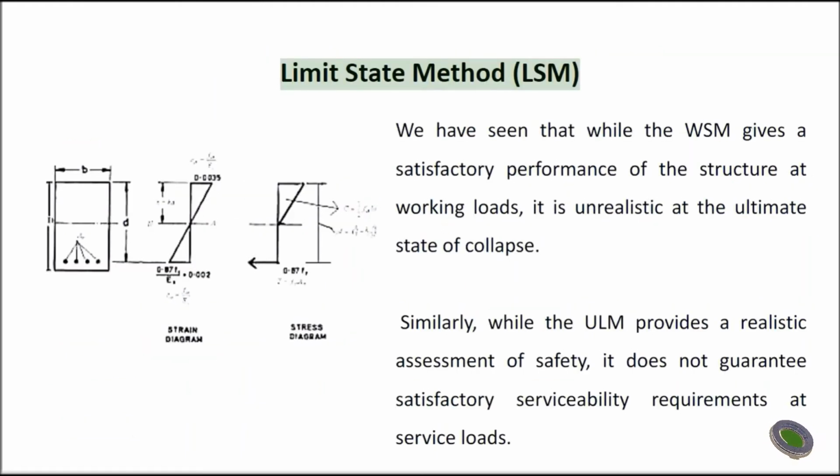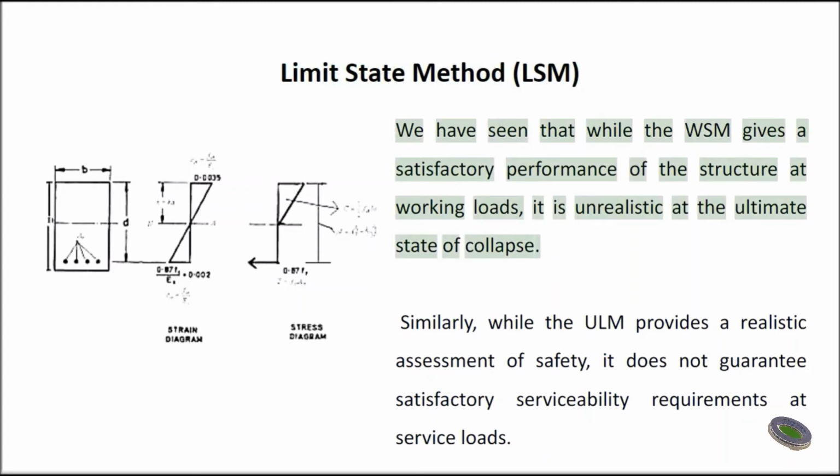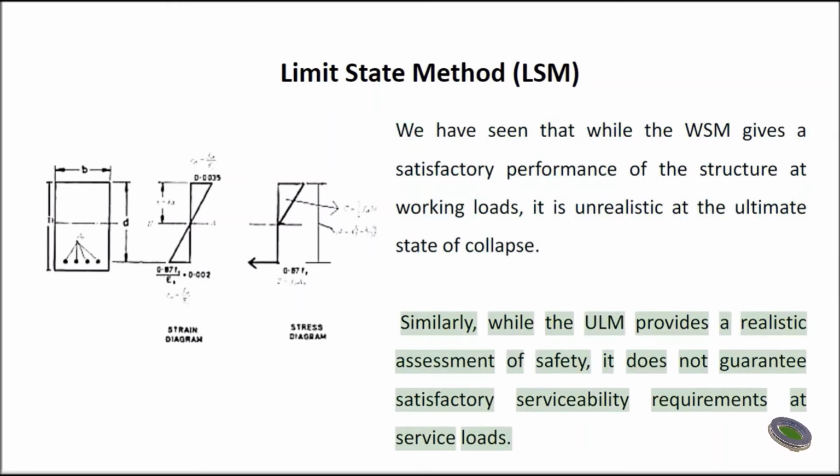Limit state method, LSM. We have seen that while the WSM gives a satisfactory performance of the structure at working loads, it is unrealistic at the ultimate state of collapse. Similarly, while the ULM provides a realistic assessment of safety, it does not guarantee satisfactory serviceability requirements at service loads.